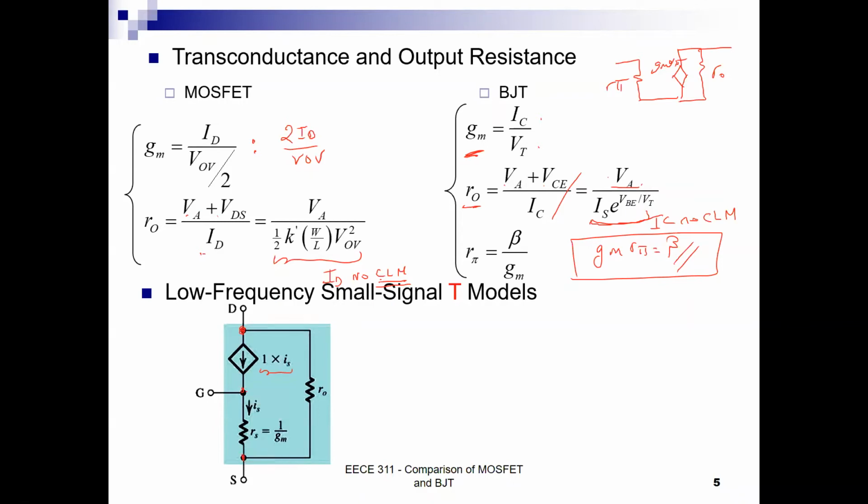This means automatically that this current equals 0. It's also telling me that when looking here, the voltage between this node and this node is VGS. So I can figure out that IS is nothing but VGS over RS, which becomes GM times VGS. So it comes back to the notion that ID is GM VGS. Now we plugged in a resistance here, which without RO will make some easier way to solve some problems.